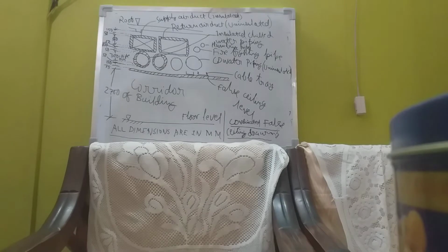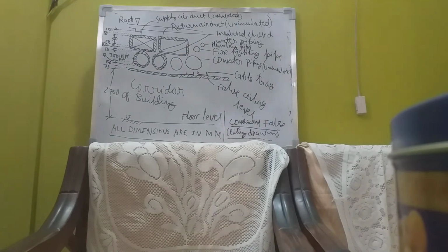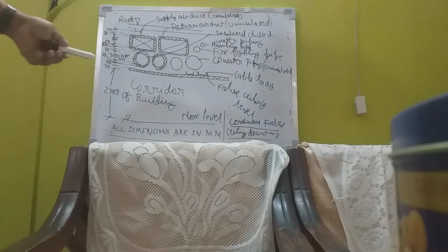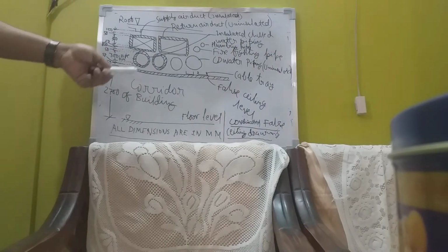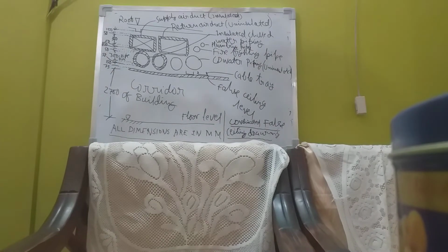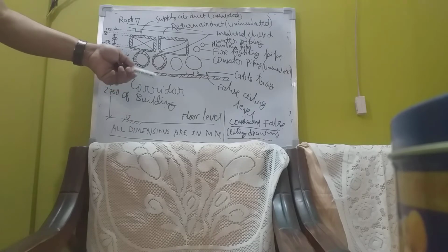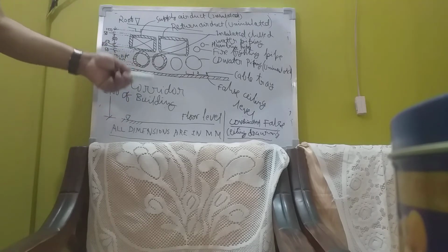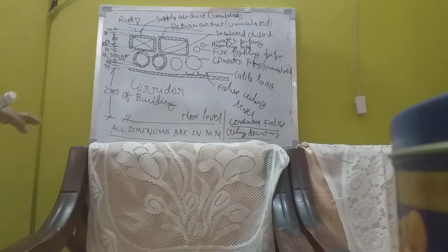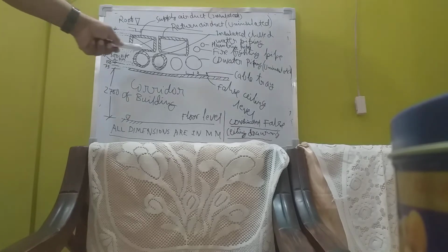But in a corridor, getting 3000 mm in a place like Nehru Place or a congested place like Palika Market is difficult. So there, if you get 2700 mm, you are lucky. You can understand, a 6 feet man walking here gets around 8.5 feet height. So it's just okay. He can feel comfortable. He won't feel that the false ceiling is falling on his head.